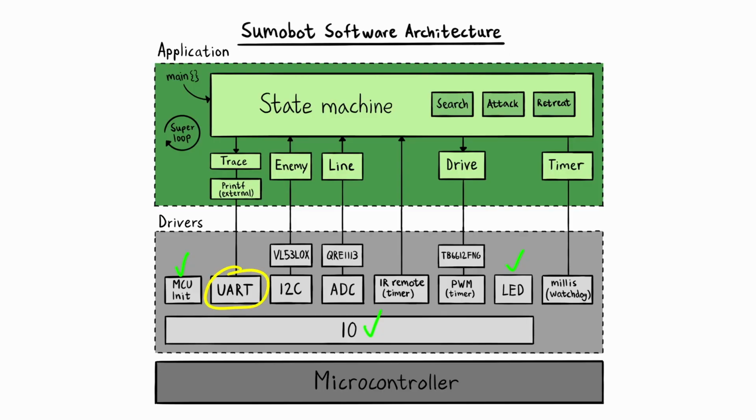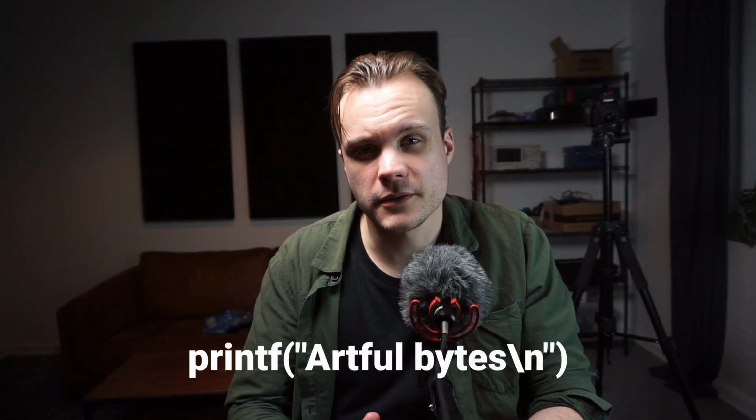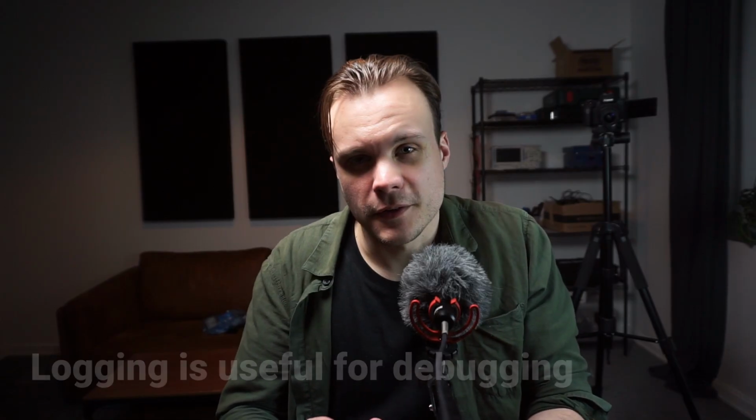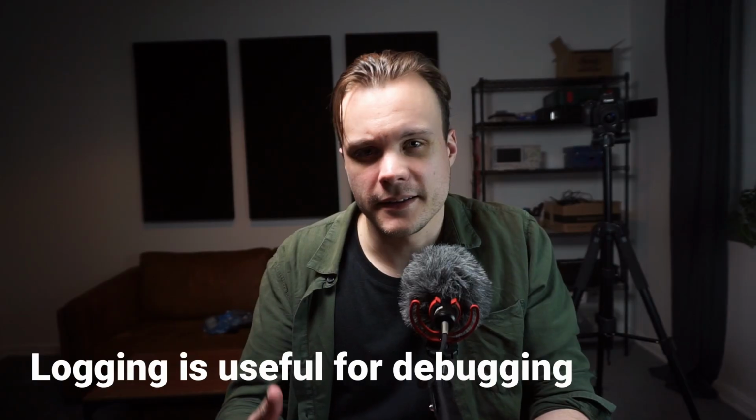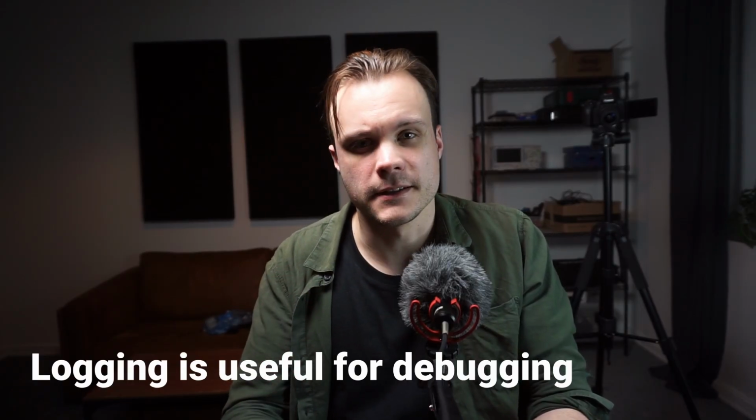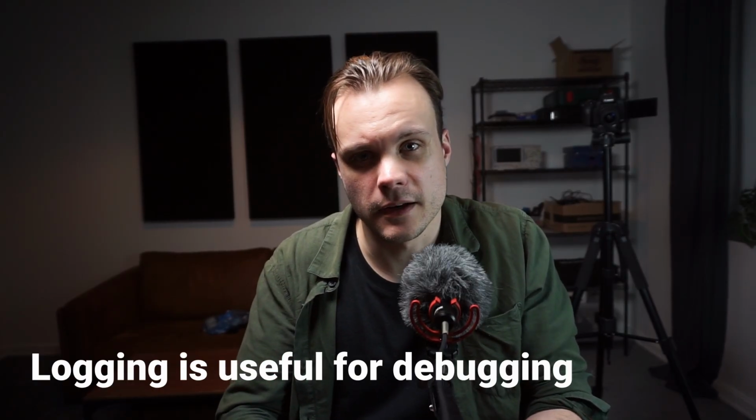More specifically, I'm going to write a UART driver, and my end goal is to be able to write a single line of code to print a string to the terminal. And printing strings or logs to a terminal is another one of those things that are nice to get set up early in an embedded project, because similar to having asserts and being able to blink an LED, it's another one of those debug facilities that are nice to have during development.